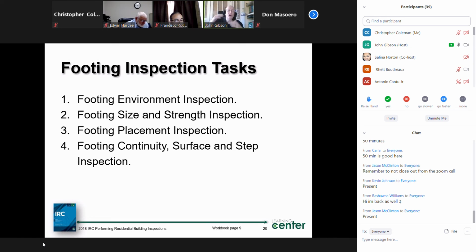So we will call for, if it's more than a 1 in 10 slope, for example, in the code, then it says you need to break that into stepped footings so that it goes across, drops down another footing, drops down another footing, instead of trying to do one that's on a slope, which is more than 1 in 10. And that's the idea behind the code section.